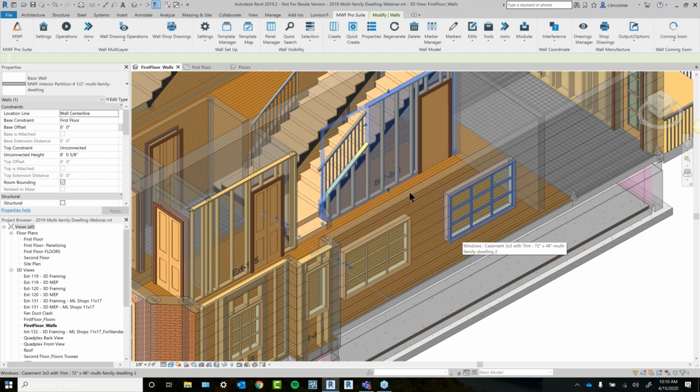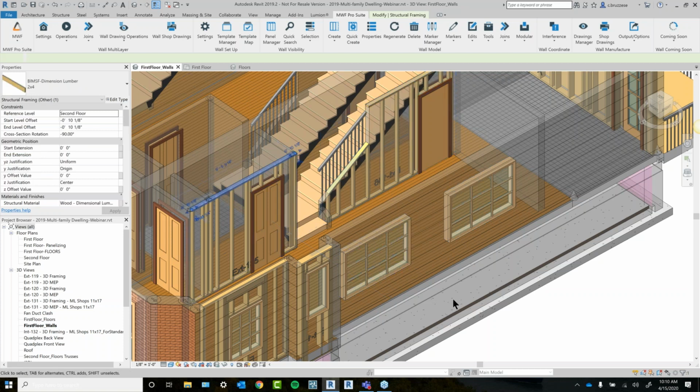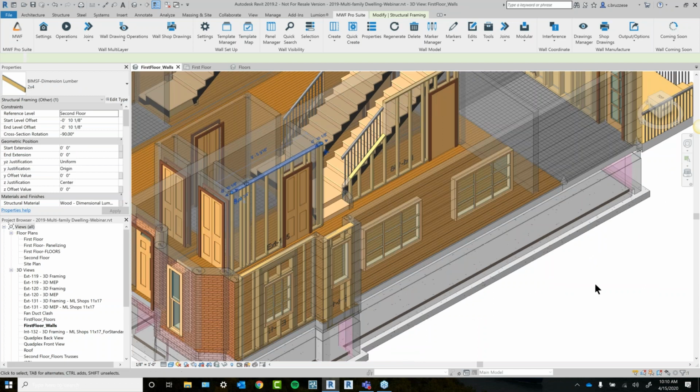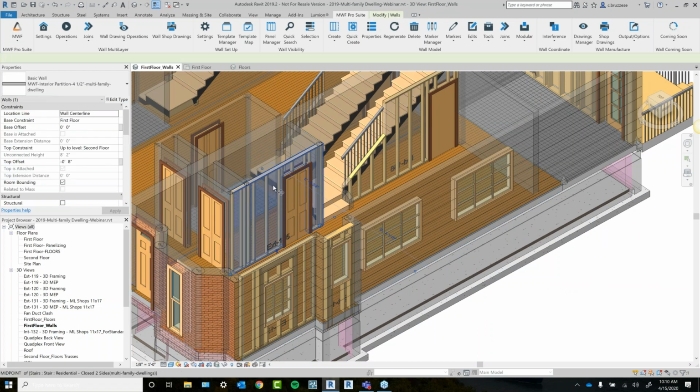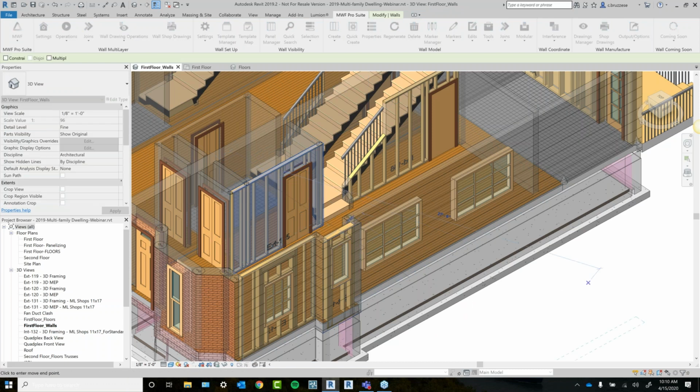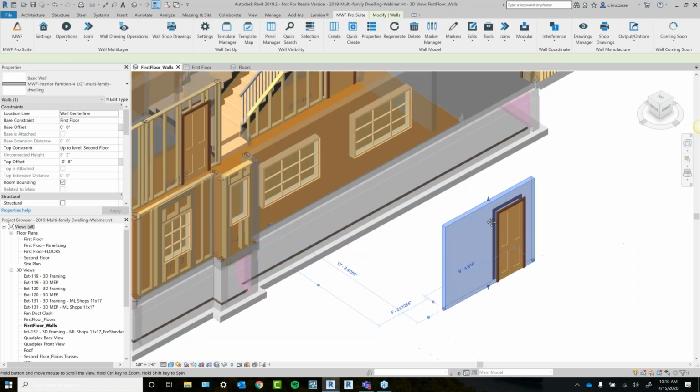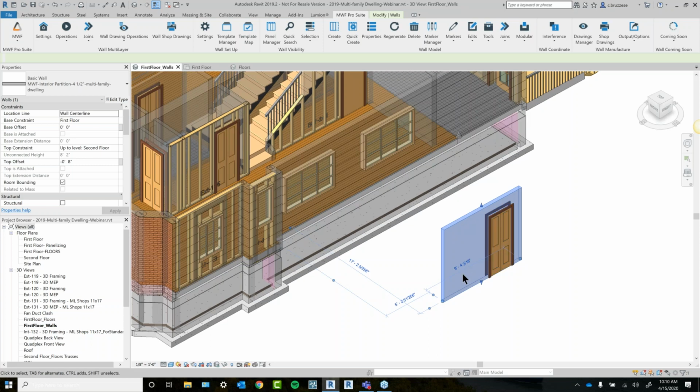This is where a dummy wall can come into play. Like I was mentioning, you can create some separate walls off to the side of your project and leave these unlocked, so you can make any necessary modifications.